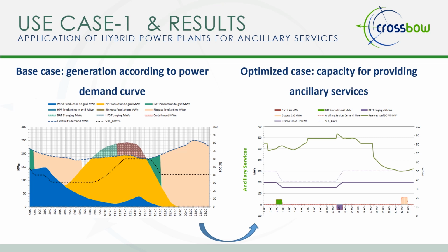More specifically, the algorithm has been programmed to allocate as much energy as possible into the partition of the battery aimed to provide ancillary services. Figure left shows an example where the algorithm does employ all the stored energy at the beginning of the day, although this energy could have been used in the moment to cover the demand, instead of using the gas turbine. Nevertheless, this energy is stored to provide ancillary services during the day ahead.